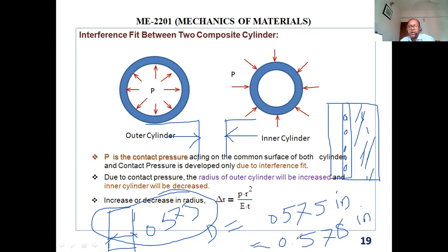Now, how do you put a rivet with this diameter in this hole? It will not go in easily. You cannot hammer it, that will not be permitted. Even in the aircraft industry, they will not allow you to heat up this panel. So the only option you have is to cool down the rivet.